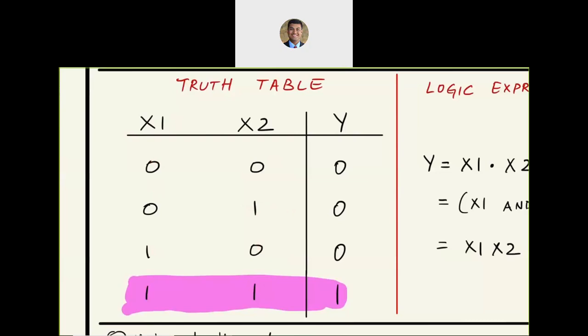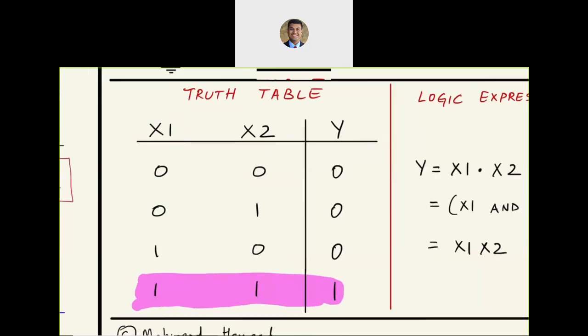And if we had more, we would go four zeros, four ones, four zeros, four ones, followed by eight zeros, eight ones, eight zeros, eight ones, followed by 16 zeros, 16 ones, and so on. So those number of zeros are going to increase in powers of 2. So that's a very neat trick if you want to look at really big size truth tables.